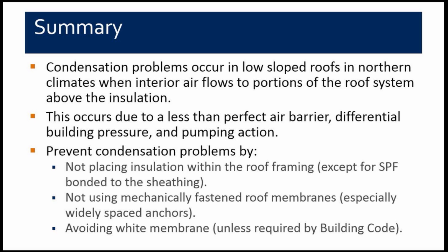In the case of the compact roof that we looked at, the pumping action was one of the bigger causes of the air movement. When it pulls it up, it brings the air above the insulation where it can condense on the inner side of the roof membrane. So theoretically, if you had a perfect air barrier, you'd have no problems. But as we tried to do, even with the method of trying to seal the deck and make it work, it just isn't practical. It's just too difficult to do. It's a lot easier when it's on the top side in initial construction.